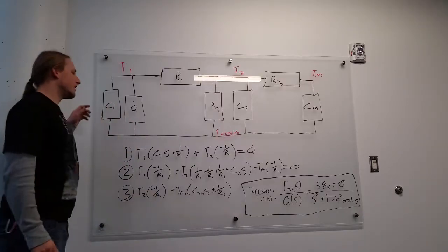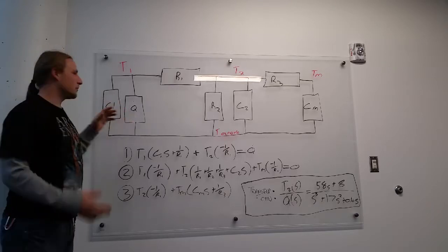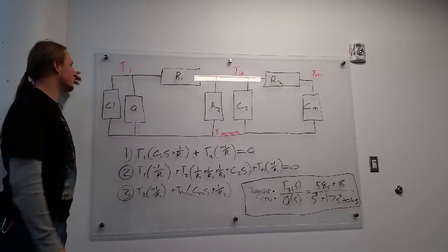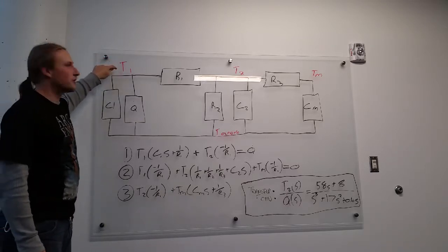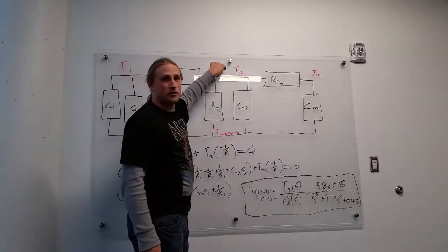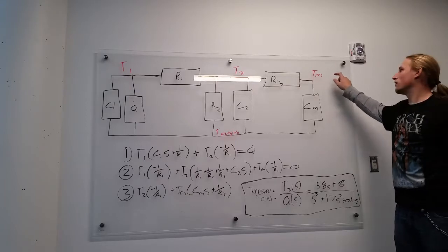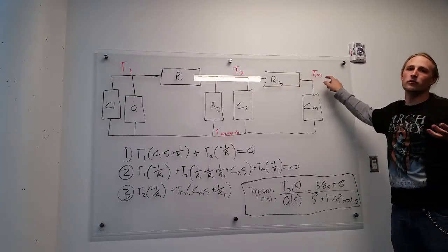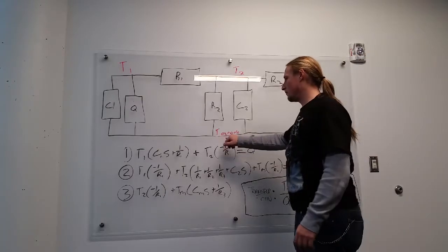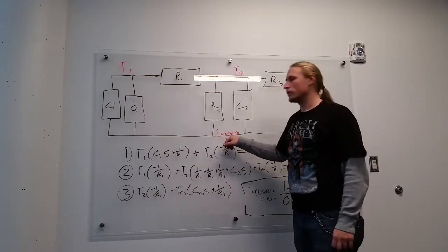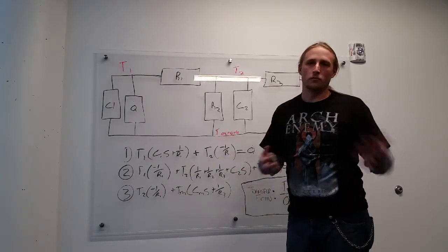Okay, so the reduction of the system that we have into a circuit model looks like this, where we have T1, the temperature inside the box, T2, the temperature inside the room, and Tm, the temperature inside the temperature sensor, the actual reading of the temperature sensor. And then we have it with reference to the outside temperature, which in our case we left at 0, just for a really cold day.